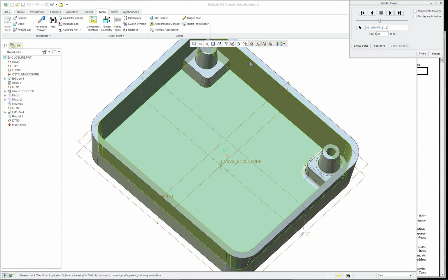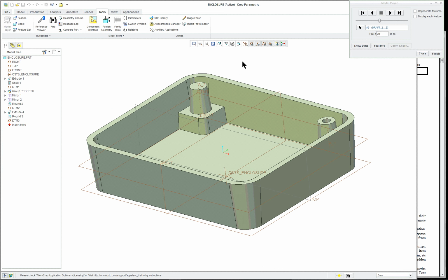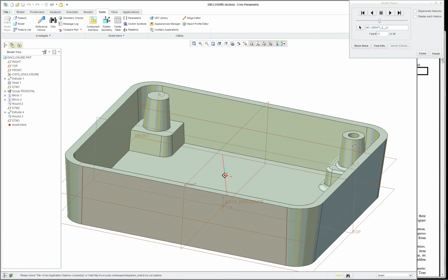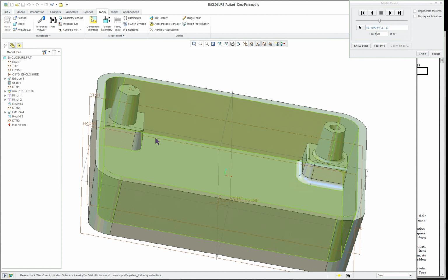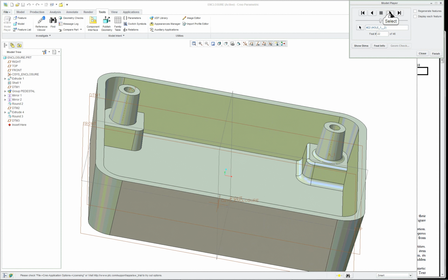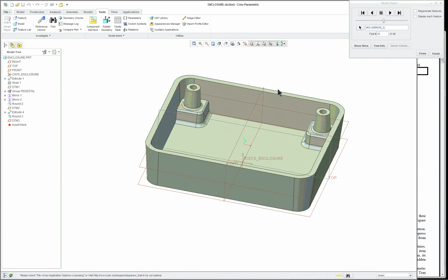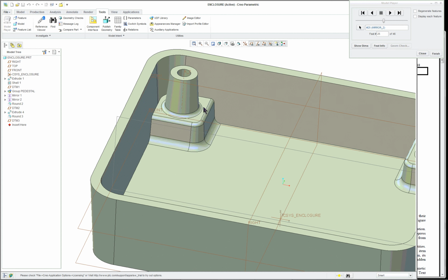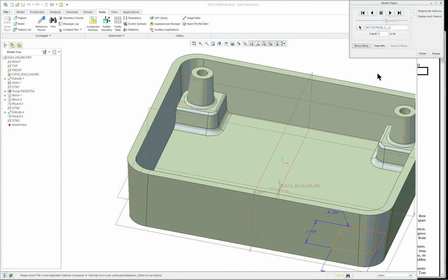It plays back a little bit odd, because it doesn't play it back as a complete group. But this has been grouped on one side here, all one unit, and then we're just going to simply mirror it. If you don't get your dimensions correct, it won't mirror all the features, and you'll get some failures with your rounds over on this side. So you want to watch your dimensions. The scheme and the sizes are very important, and they have to be precise. And next, of course, we're going to have the same thing happen for the mirror in the other direction.